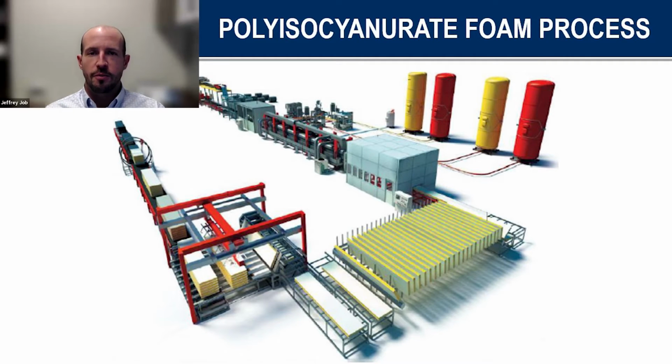I would mention too on the moisture absorption standpoint, we talked about that on the XPS side. From an ISO standpoint, the foam core itself really will not absorb any moisture. Generally, all that moisture absorption is occurring in the facer component. So if we change out that facer to something more water resistant, able to get wet and not be impacted by that, for example, a coated glass facer, then you've eliminated the drawbacks related to that paper facer.